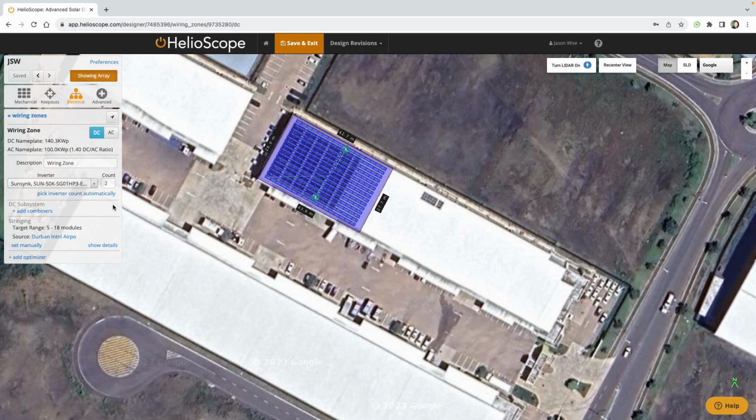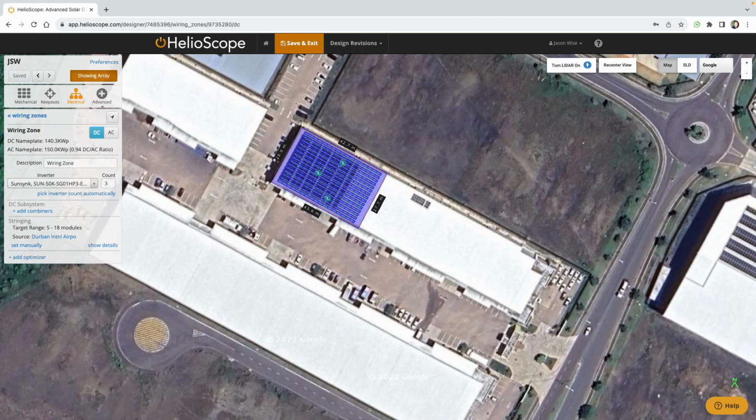Specifically, we are able to go to 130. So for the purpose of the design, we'll put 3. As you move your inverters around, can you see that the software has already allocated those panels to that PV array? So if your inverter room was going to be, for example, where these cars are, you could move these inverters there and you can see that the solar cables are moving as well. That's going to give us an understanding of the length of the solar cables and also work out any losses involved in the system.